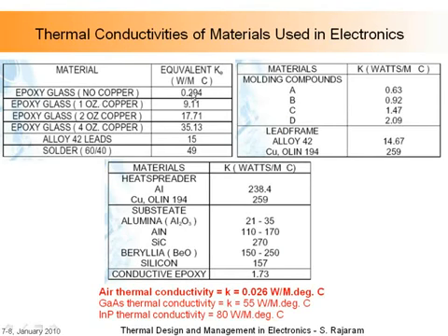The plain glass epoxy copper board has very poor thermal conductivity, 0.3. When you add some copper to it, and there's always copper in it because it has conducting planes and ground planes, it goes up to 10, and it can go as high as, say, 20. And these are the leads from the device. So these are all different compounds that make up the package compound, and these are the frame that makes up the leads. So these are all the material properties that we deal with, and you can see it varies all over the place, from 1 watt per meter degree C all the way to 100 watt per meter degree C. Just to give you an idea of the kinds of materials and thermal properties that are used.